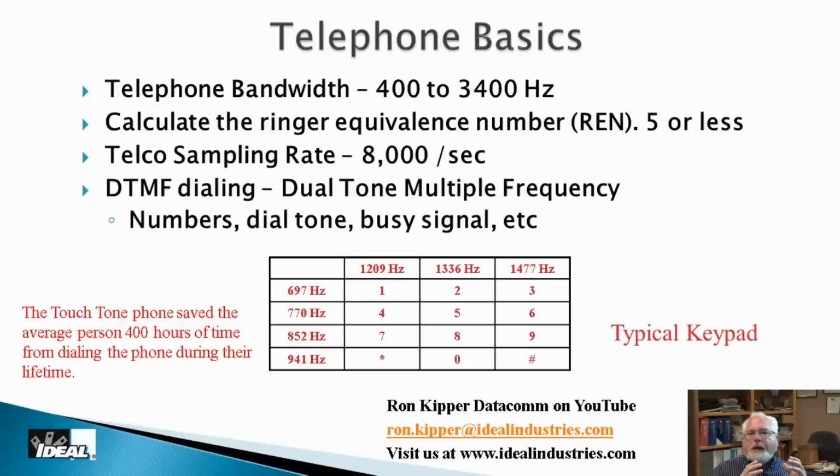Every landline phone right next to that FCC number will have an REN number as well. And old rotary dial phones, if you remember those, used to have an REN number of 1, and the local phone company back in the day would let us have a total load per house of 5. So if the REN number on the phone was 1 and they allowed 5, well, then obviously 5 phones could be used, and all 5 of us should be able to talk to Grandma. Now, if we got beyond those numbers, well, then we'd start having issues.